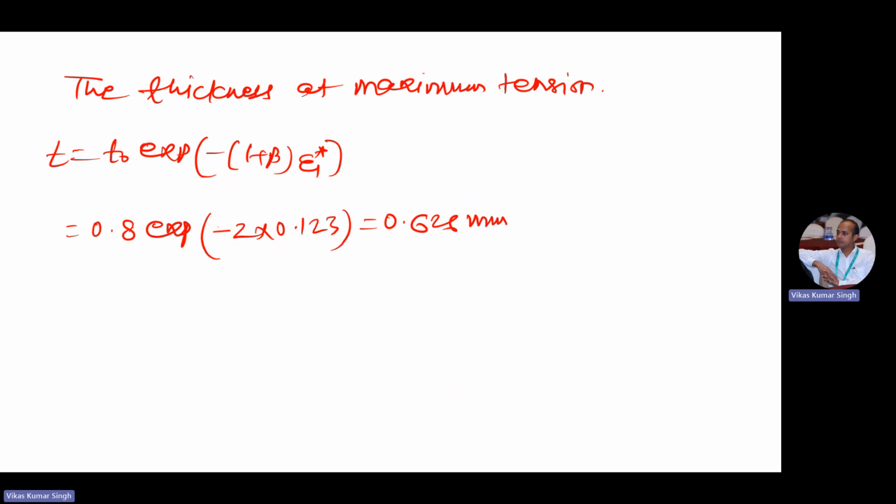And now if we are further moving, calculating a tension T1 and T2, as we have already discussed. So T1 in the case of plane strain case, sigma 1 by T. And now if this is major tension and T2 is the minor tension, so from the ratio of this, one more formula is there, like alpha, we can write alpha equal to T2 by T1, where T is the thickness in case of sheet metal process.